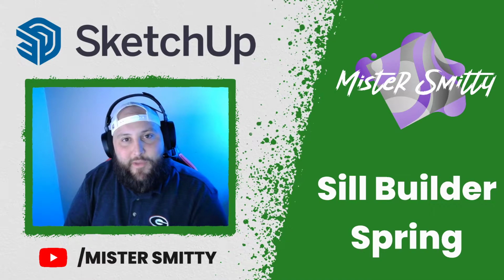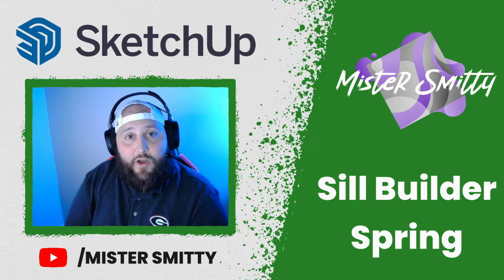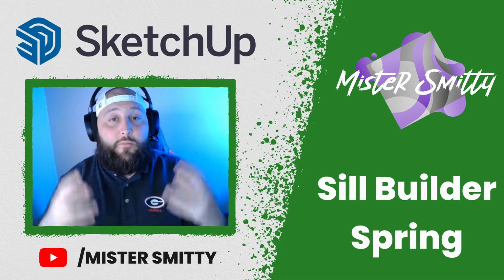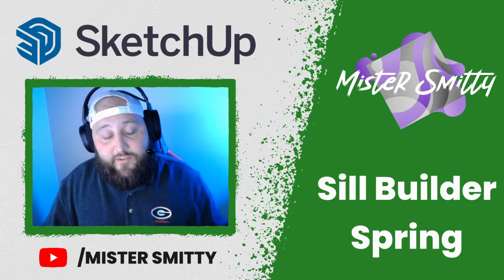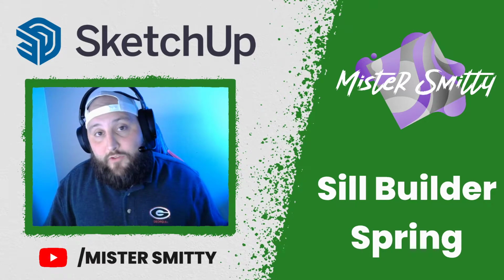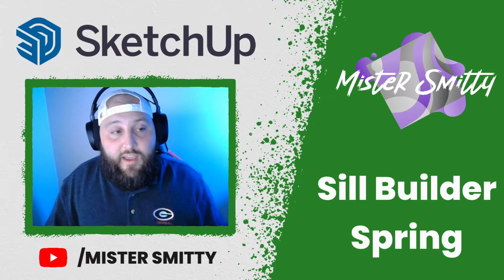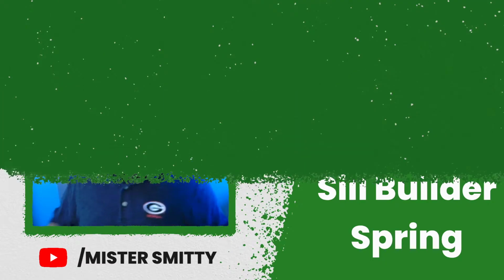Everybody, Mr. Smitty back with another skill builder video where today I'm going to be showing you how to 3D model a spring. The purpose of this series is to introduce you to some new skills that you haven't seen yet in Google SketchUp, and today we're going to be looking at creating arrays with a rotate tool, and we're also going to look at how to curve some edges and reverse faces as we use the Follow Me tool. Alright, so let's just go ahead and hop right into it.